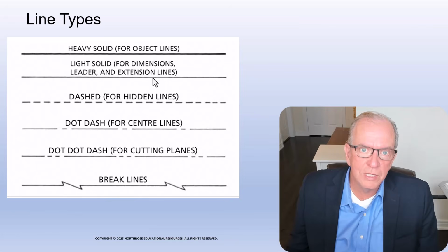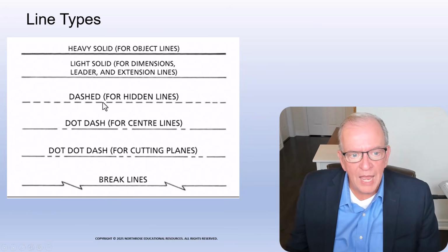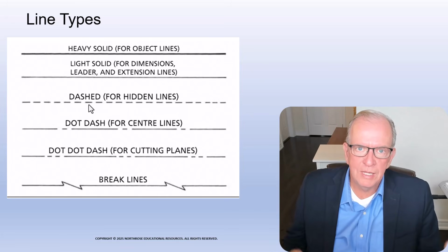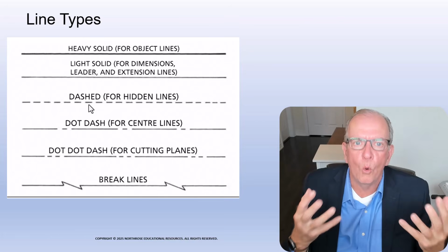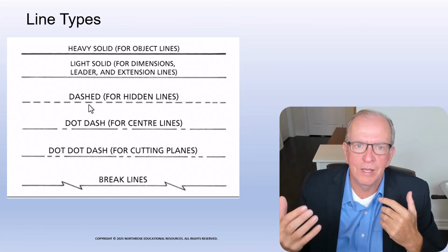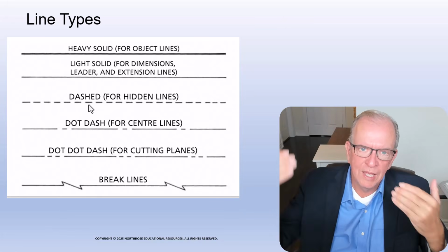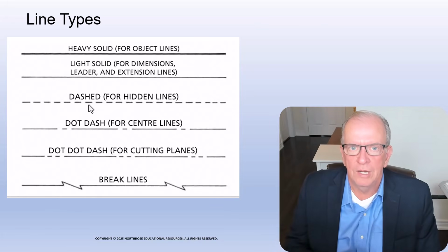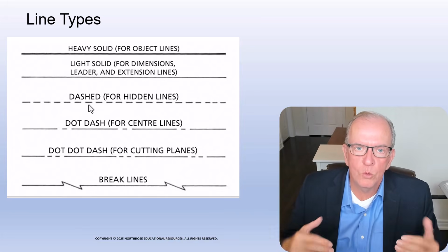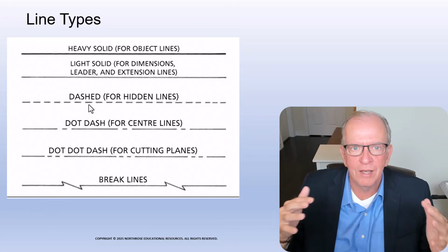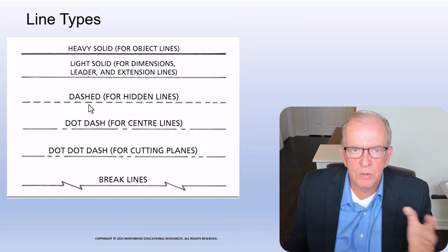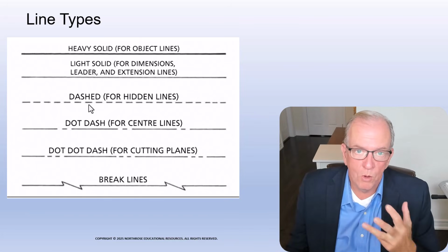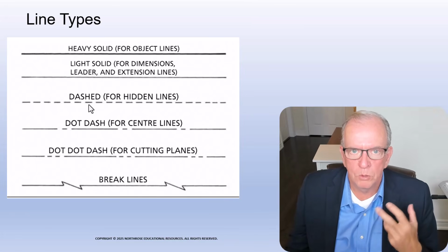So how long is this wall? It will tell you, right? Dash lines are for hidden lines. Dash lines basically mean something is hidden behind something that the consultant, the architect, wants you to know, right? It's not that everything that's behind something will always be shown with a hidden line. It's like, I want you to know this is underground. I want you to know this is under the concrete slab, that kind of stuff. All right. So that's very important because hidden lines will tell you information about things that are underneath other things. So we definitely want that to come out, right, when we're looking at things.